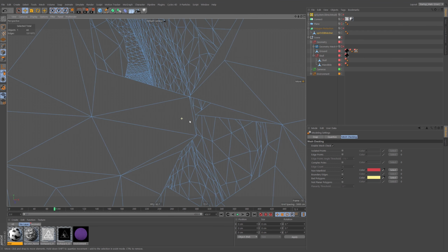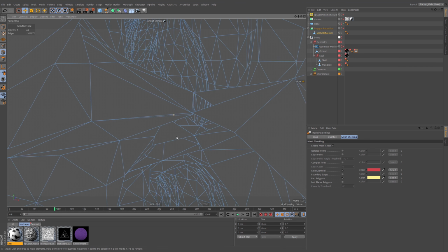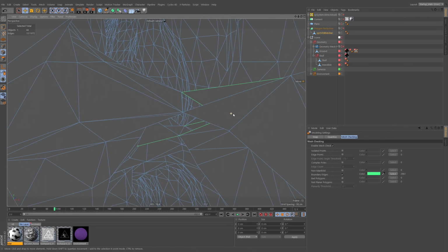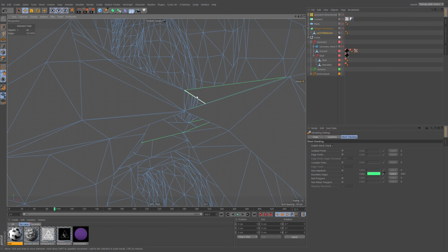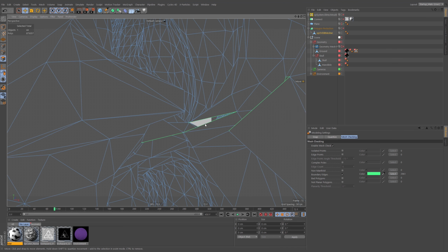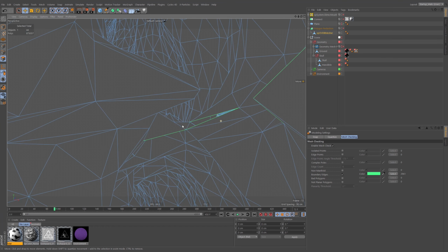And now we don't have any more non-manifold edges, but we do have gaps in our mesh. So let's turn on boundary edges again. And you can see that's where our boundaries are. And we can just seal these up using some classic operations. But right now, you can see that we've got a problem where it's branching across, and to be honest, I'm just going to delete these polygons. This is just a bit of mesh cleanup that if you're finding any of your mesh operations are failing, this is a very likely candidate. And it's pretty rare. You might have it, but I think it's worth me showing you just so that if it happens to you, we can get out of that scenario.